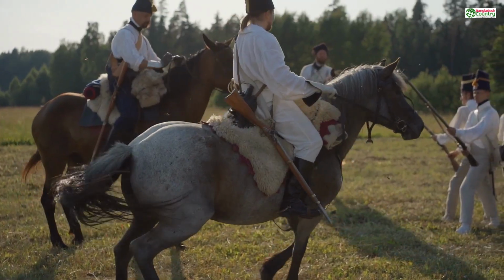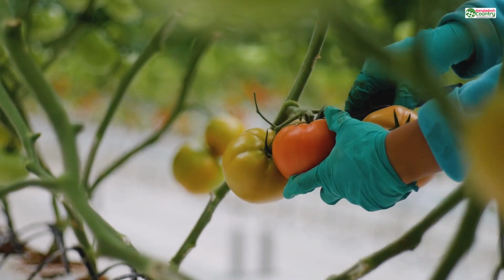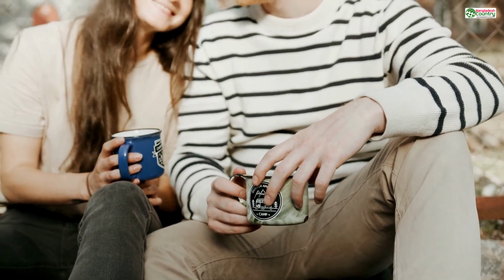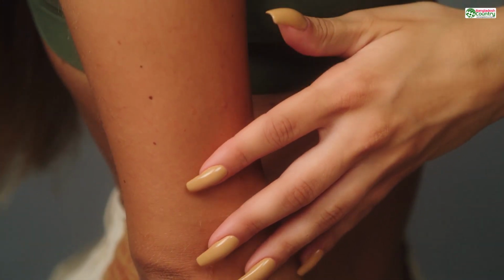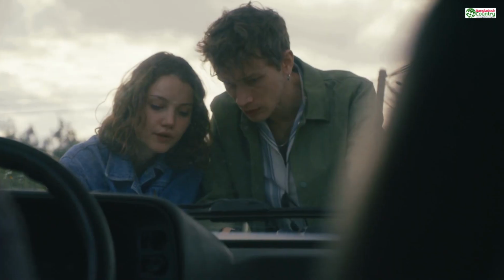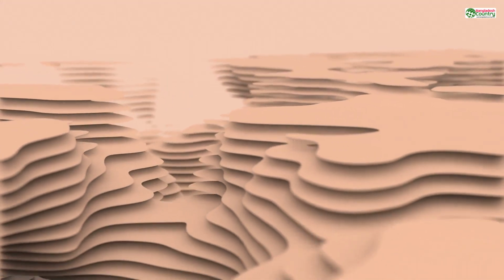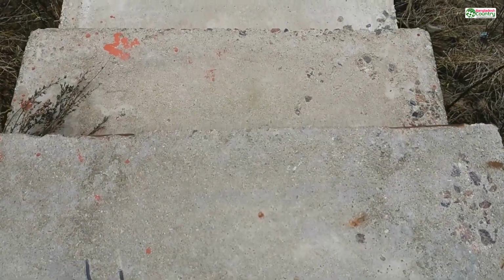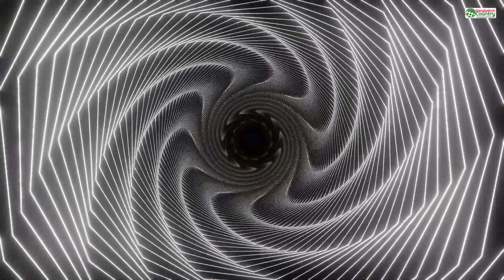Let's break that down. First, let's talk about high quality. To get that beautiful, smooth finish, especially on curved or angled surfaces, you need a low layer height. Something like 0.1 millimeters, the thickness of that single sheet of paper. With layers that thin, the stair-stepping effect on a dome or a slanted surface becomes almost invisible to the naked eye. Each step is so tiny that they blend together, creating the illusion of a perfectly smooth curve. This is the setting you choose for detailed miniatures, for presentation models, for anything where the final look and feel is the absolute top priority.